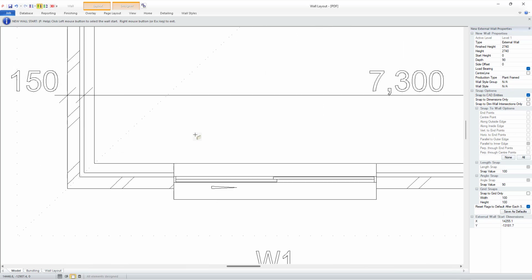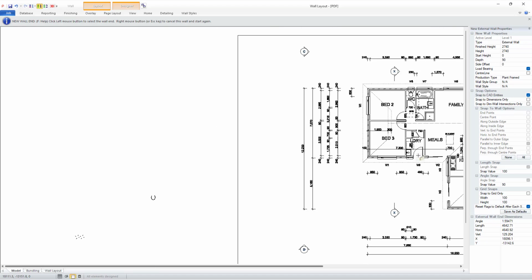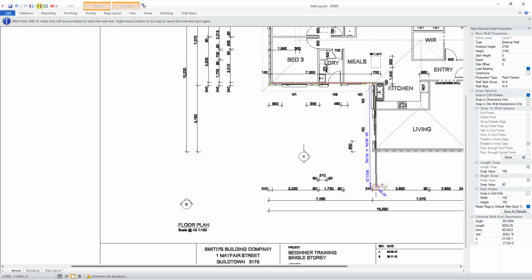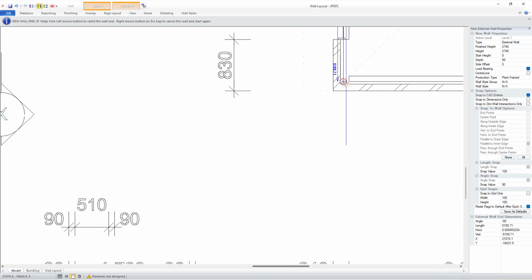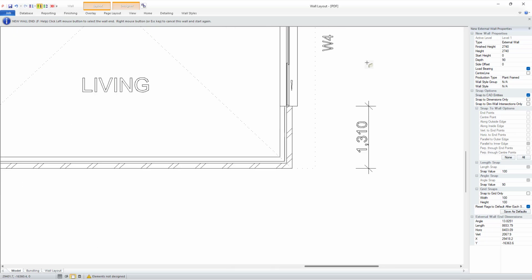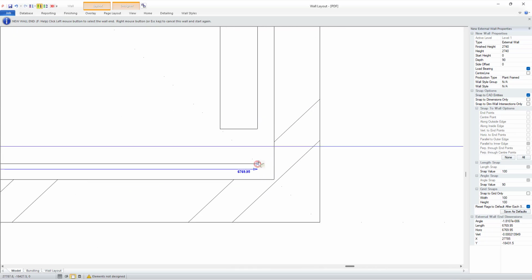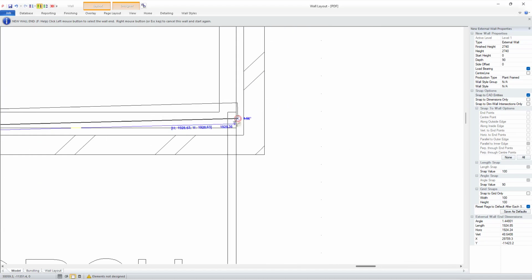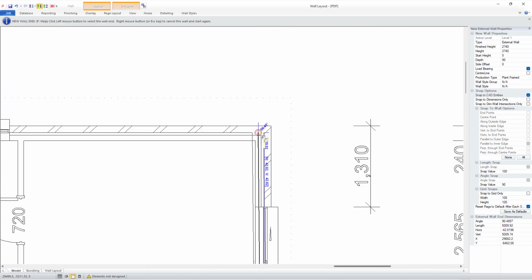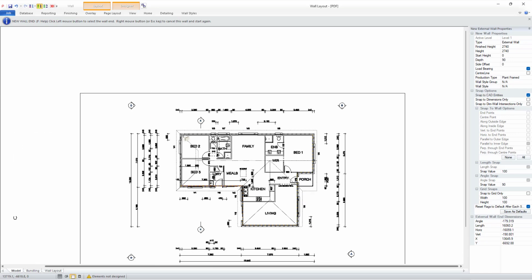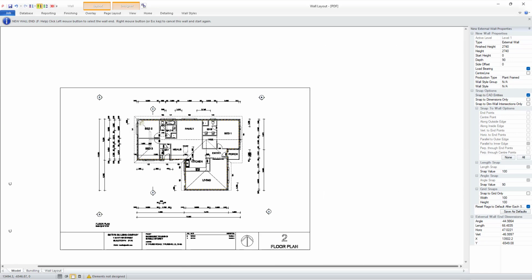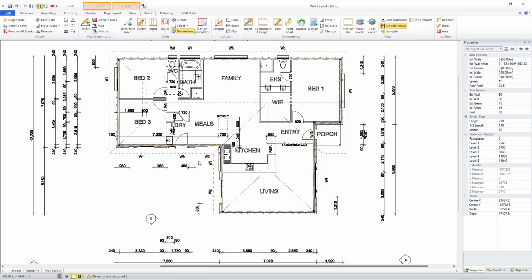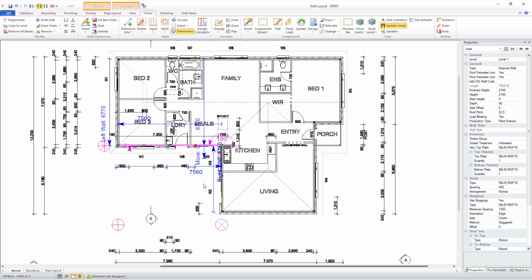Now, this does come with some caveats. Not all PDF files will vectorize perfectly or at all. PDF files that are scanned from paper plans are not going to work. PDF files created from CAD files are more likely to work. You'll need to check the accuracy of the scaling. It would be worth checking a few dimensions like I did and confirm that your walls are correct. In addition, you always need to refer to the original file as the vectorized process could lose details in a drawing, especially if you're hiding curved or filled entities.